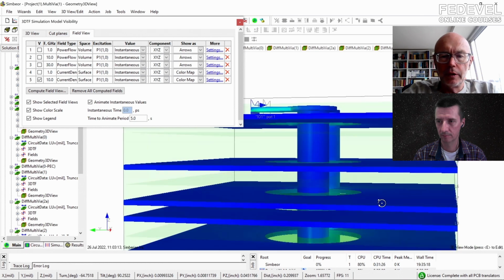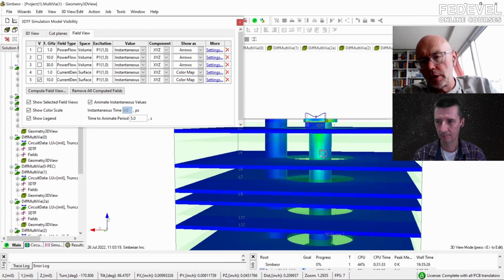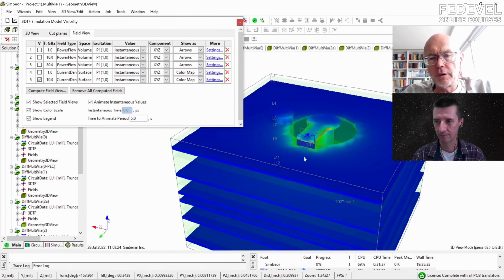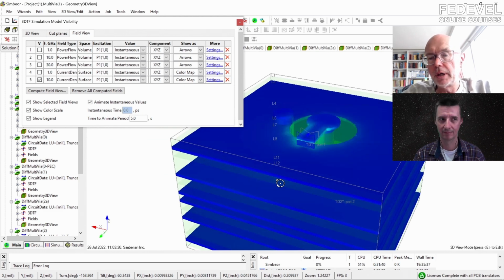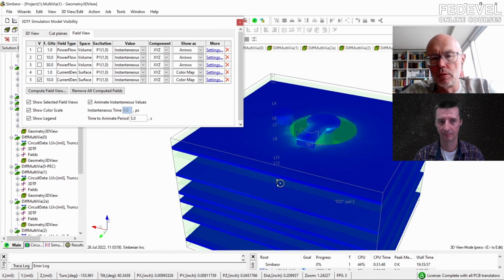It's always a good idea to have stitching vias nearby. That provides the bandwidth we need. But differential is maybe even better. I can see designs now both in differential and in single-ended. Single-ended provides more space, and if you have some kind of micro manufacturing technology, you can basically localize it quite well and get through without any problems. So save space.